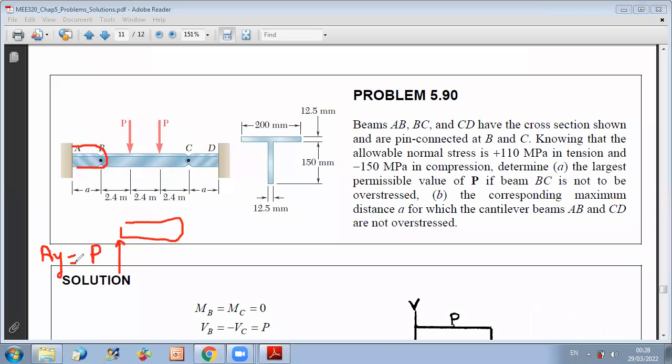When you treat part AB, this is an equilibrium and you don't have a bending moment at B. M at B is 0. So you can use that the bending moment at B is 0 to get the moment reaction at the fixity. For this part of the beam, sum of forces equals 0. So at B, the reaction, or the shear, if you want, is downward. So you have a value of shear equal to P.